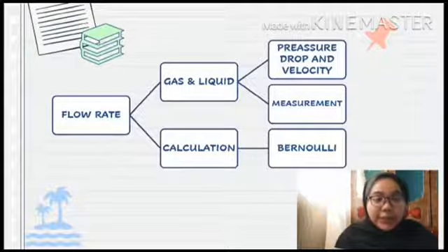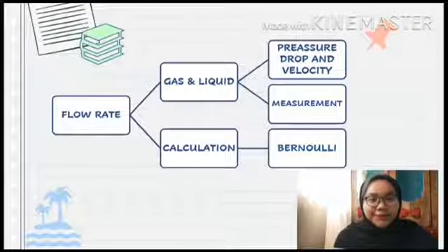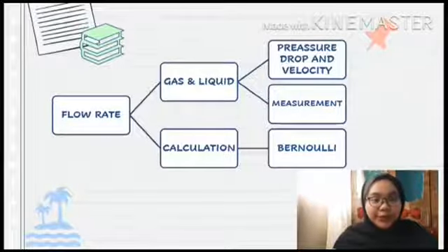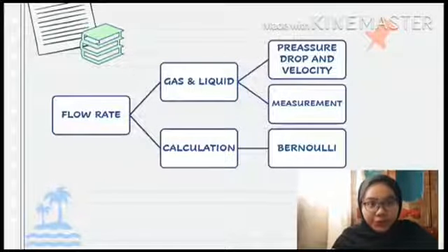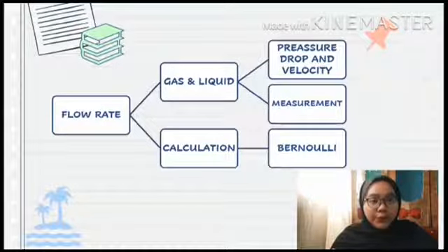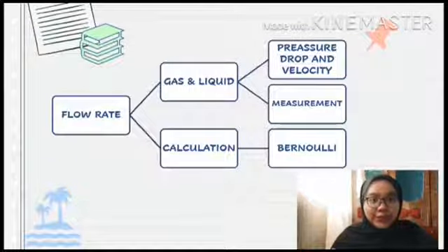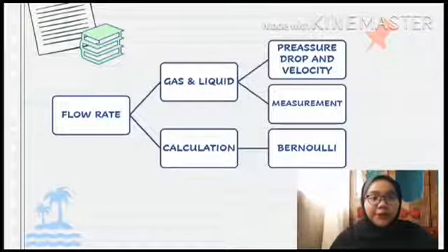Next, based on our calculation, we use a flow meter to measure the flow rate. This measuring technique, operation and characteristic are determined by comparing the pressure drop, which is related to the velocity of the fluid in the pipe. We used the Bernoulli equation to calculate this. The pressure drop is measured using a differential sensor, and when it is calibrated, it becomes a measure of flow rate.